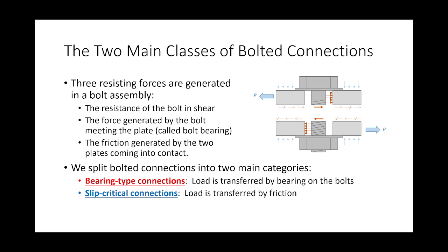We call that bearing. It is bearing on the plate. So there's actually a bearing force between the bolt and the plate, and that is a resisting mechanism. We call that bolt bearing.